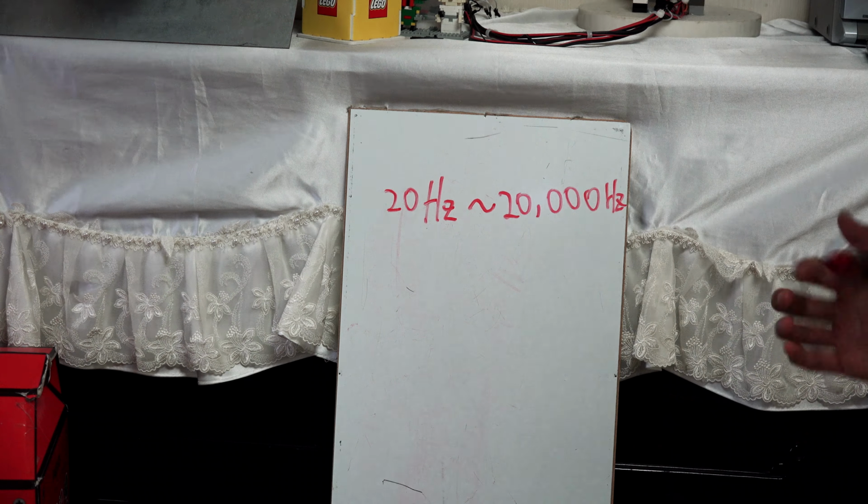So I will connect it. First I will just put VCC in 5 volt. And there is a ground here, and I will put ground in GND.